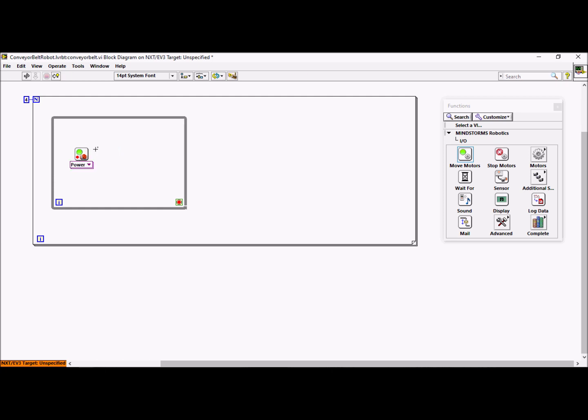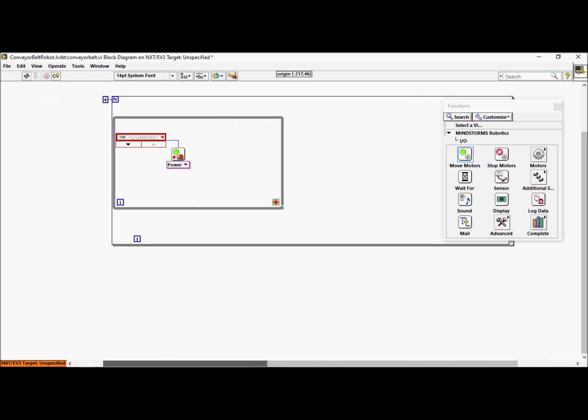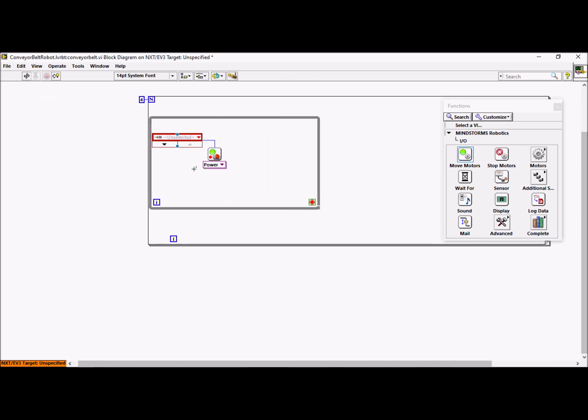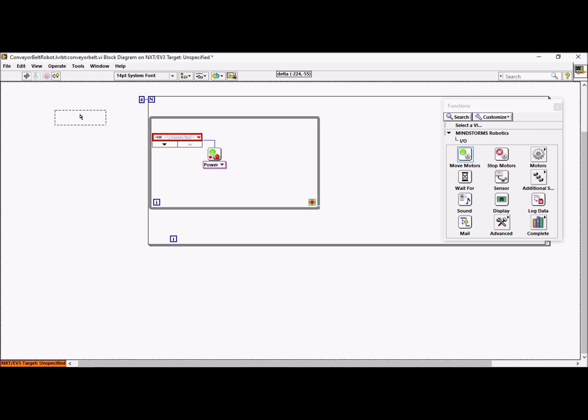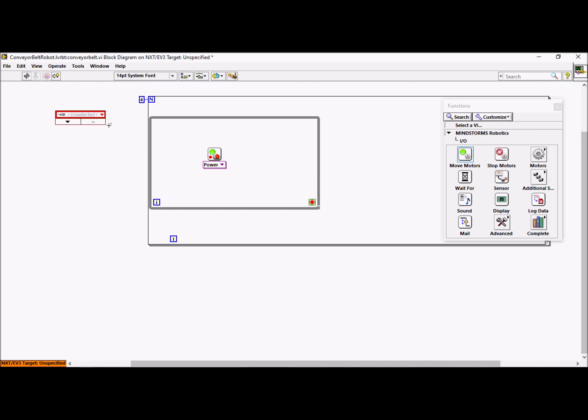And then I'm going to create a constant on the top node for motors. I want to be able to use these DC motors anywhere in my program. So I'm going to select that initialize box and move it to the very outside so I can access it anywhere in my program. But I do need to reconnect my wire. So we have 2 motors. I'm going to click the down arrow, and I want to choose my left wheel and my right wheel for my DC motors.